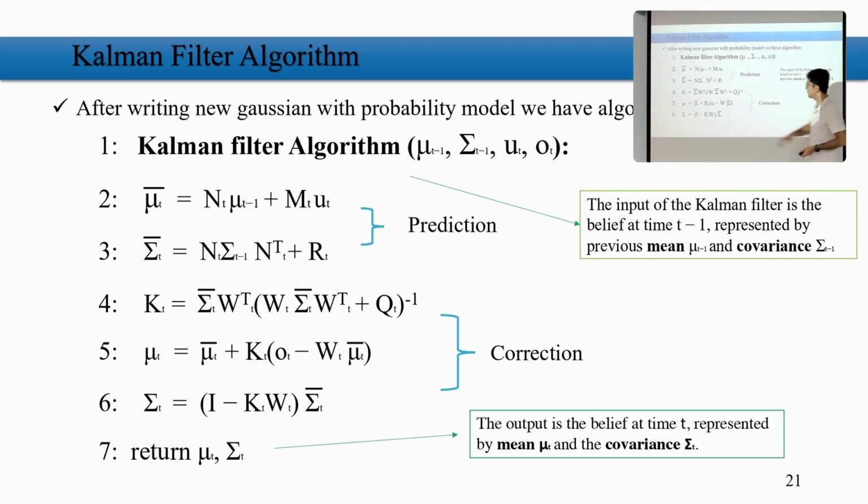In the correction step, first we calculate the Kalman gain. And we said that the Kalman gain indicates how important the control command is and how important the observation model that I have is. So again, my robot moves from here to here, sees, and in order to update, I'm saying now either the observation is more important or the one that I came from is more important.